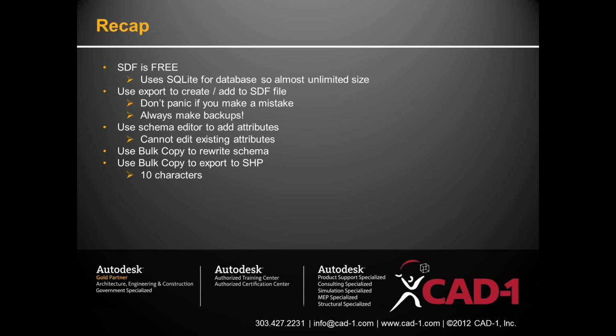It's a quick recap. The benefits of building your free GIS: SDFs are free. And the cool thing is that they use SQLite for the database. I don't know if anybody knows that, but they use SQLite systems for their database. So as far as the size goes, you're pretty much unlimited. So you can throw anything in there. Use export to create or add to. Remember, append in SDF, but don't panic if you make a mistake. You always want to make backups, but if you make a mistake, you can always use that bulk copy to clean up what you're doing.